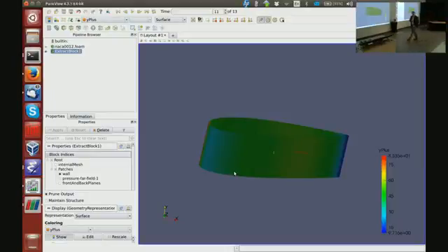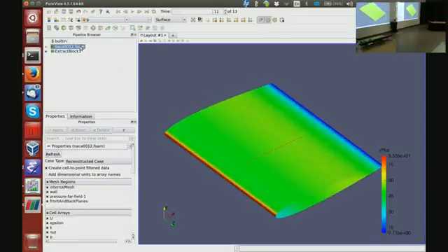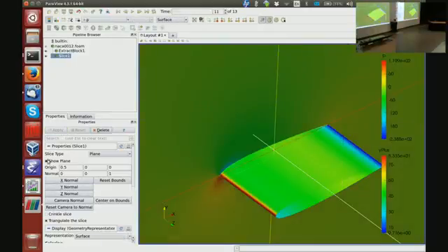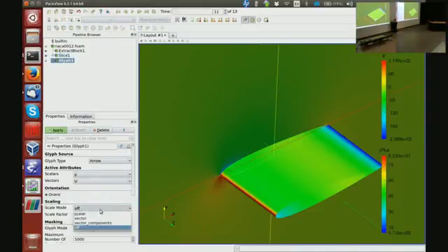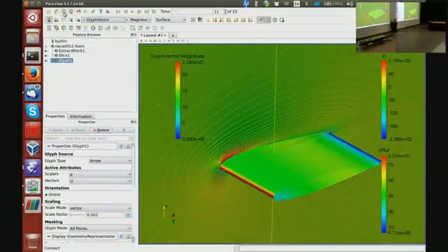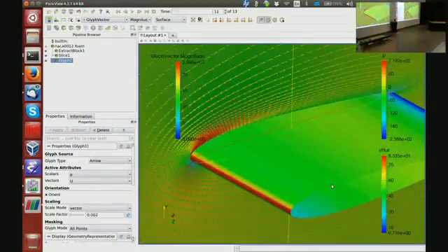Okay. The second thing that I want to do is visualize some vectors. So I'm going to jump back onto NACA 0012, do a cutting plane, Z normal, Y. I usually switch off the whole plane, because otherwise if you grab it, you move it. Okay, and again, I can go scaling, all points, 0.002, apply, color them with glyph vector. Okay, and here is a nice picture.